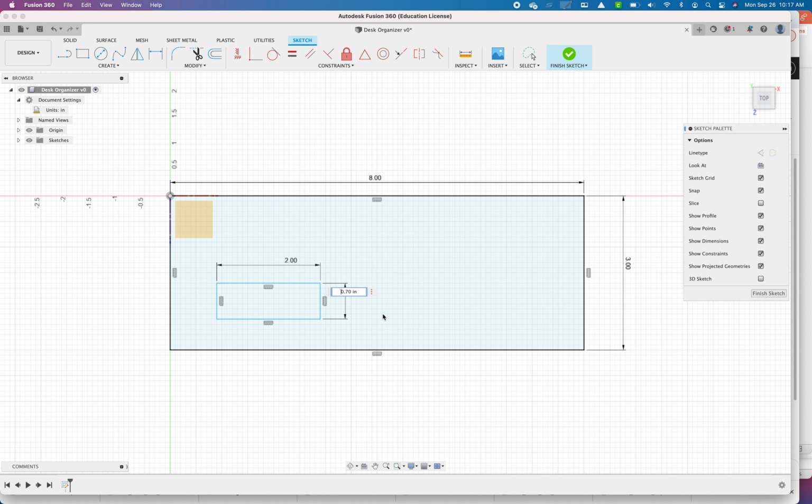And another one here at 1 inch. Notice as I'm clicking here, I'm clicking once on the line and then once to say this is where I want my dimension to show. You can also do a form of dimensioning that involves 3 clicks. If I want this line, click, to be a certain different distance from this line, click, and I want to show that over here, click, I can do that using the dimension tool too. Click, click, and click.